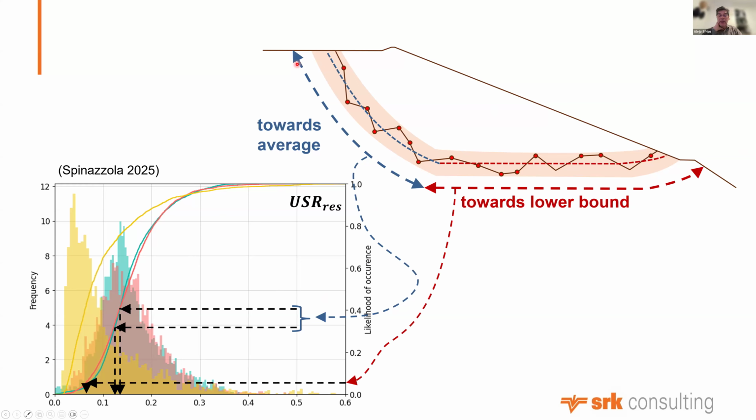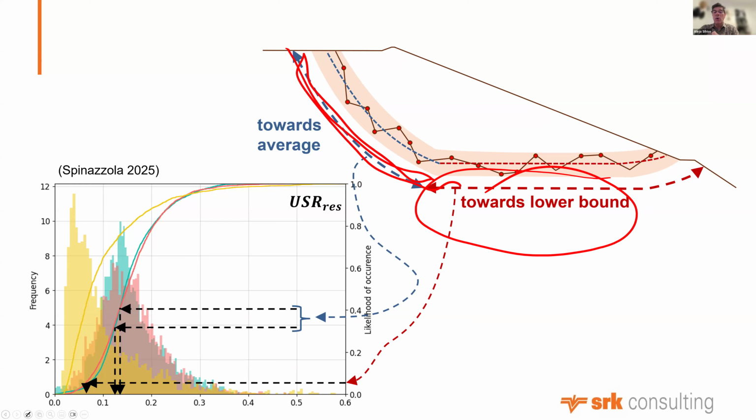So in this case, you will have to use here at the base a cautious estimate that is based on statistics. It's not just engineering judgment. Engineering judgment applies, but it's not what rules. So you end up doing more or less the kind of thinking that we would have used in the past, with the difference that we would have picked this value and applied it to the whole dam.